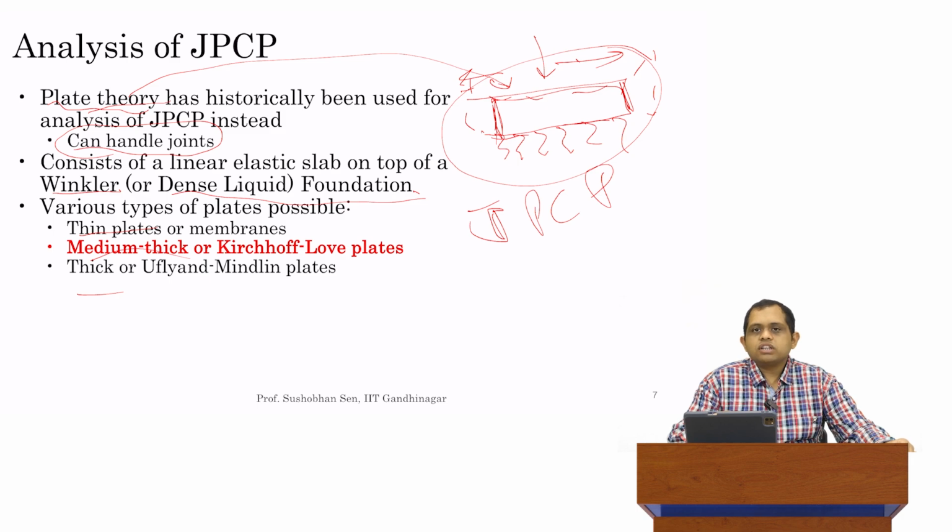So that brings us to the second possible plate theory, which is medium thick plate theory, sometimes also called Kirchhoff-Love plate theory. The two gentlemen, Mr. Kirchhoff and Mr. Love, developed these theories separately, and that's why the theory is jointly named after them. The characteristic of the Kirchhoff-Love plate theory, as we shall see in the next slide, is that we do not allow any shear stresses to develop in the cross section. We'll see the significance of that in the next slide.